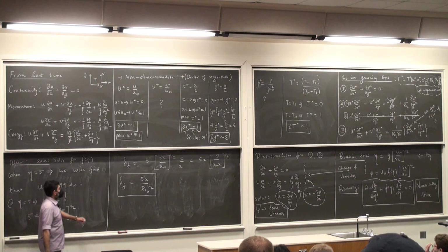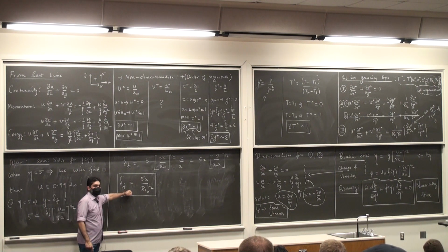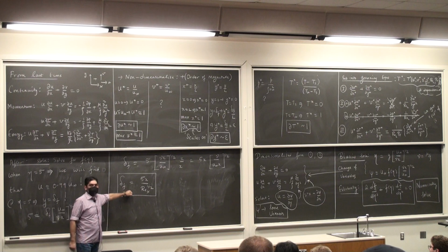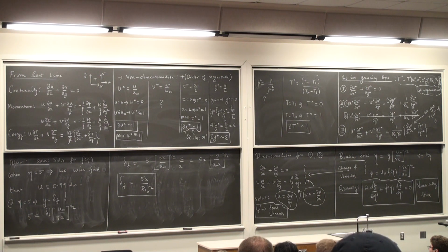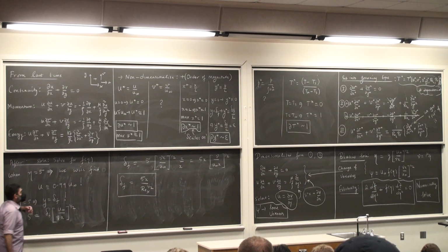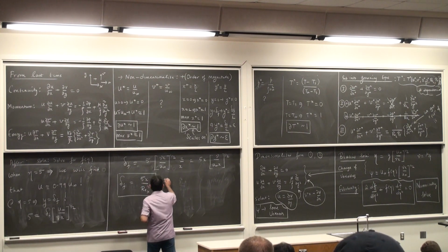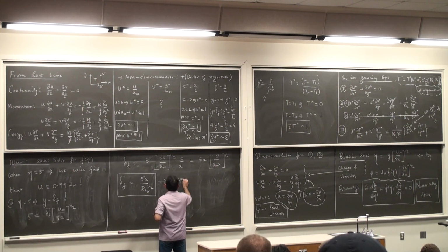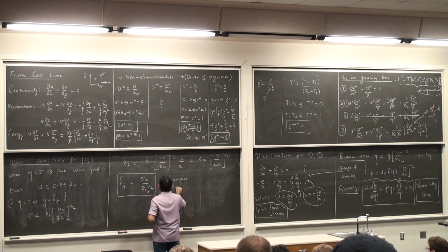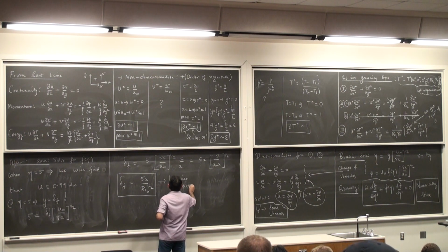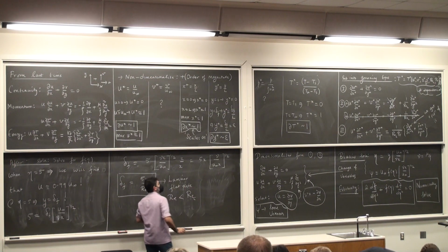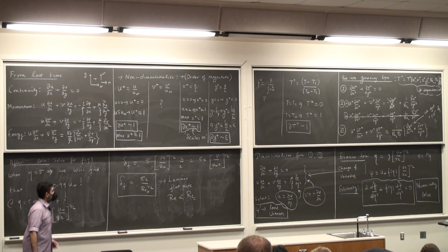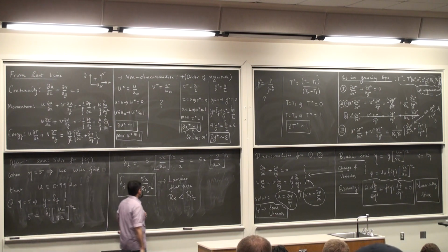and my question to you is, have you come across this in fluid mechanics? This is something that you would have seen and you would have used multiple times. And this comes from all of this hard work. Okay? So this is valid for laminar flow, flat plate, Reynolds number less than the critical Reynolds number, which is typically 10 to the power 5 for flat plates.